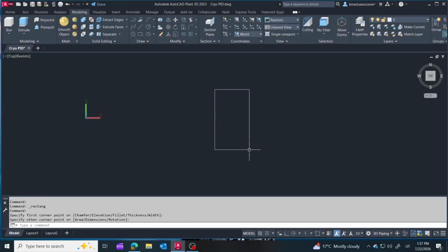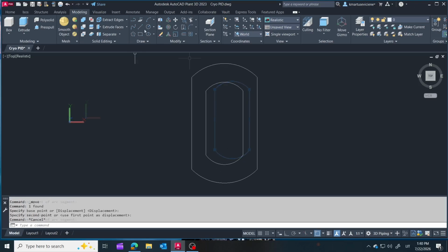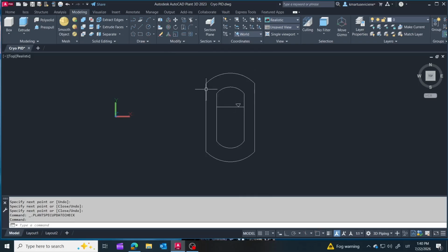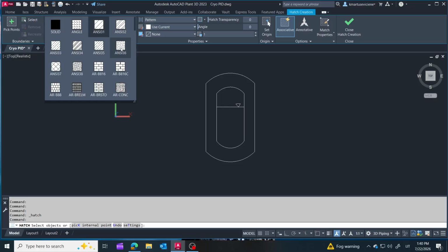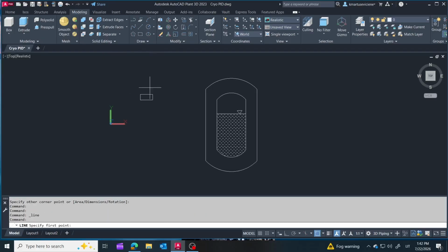At first glance, it looks like a simple vessel, but in reality, it's built as a double-wall tank. The inner vessel stores the liquid nitrogen, while the outer shell creates an insulated enclosure around it. The space between these two walls is evacuated to a high vacuum. Combined with multiple layers of insulation, this dramatically reduces heat transfer from the environment. Without this insulation, liquid nitrogen would continuously absorb heat, boil rapidly, and create large amounts of gaseous nitrogen. The entire purpose of this tank is to keep the product as cold as possible and minimize boil-off losses.